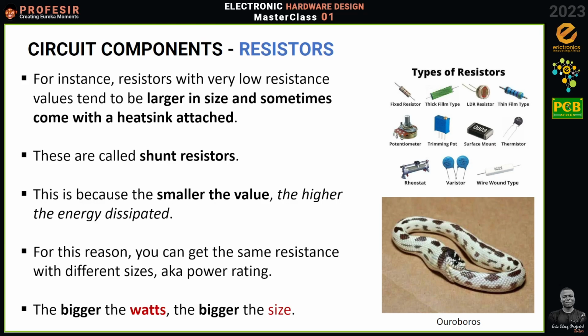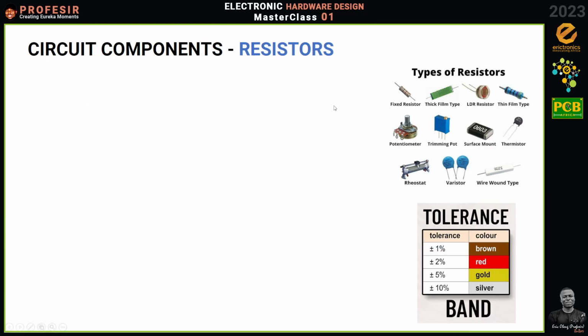Is that okay? So you don't just go and say, okay, please, I'm buying a resistor at a value of 100 ohm. No, you should also consider how much power that resistor is going to be dealing with. Okay, all right.